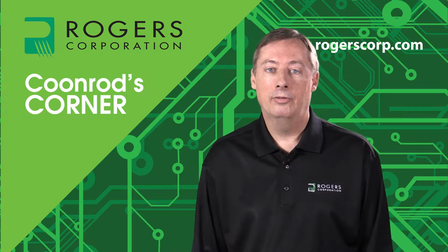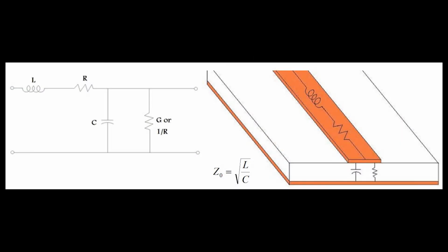So to begin with, let's go through some of the basics of impedance. Shown here is a circuit and also a schematic that is representative of the circuit. The schematic is an RLGC schematic, which means R is resistor, L is inductor, C is capacitance, G is conductance. I have that drawn over a circuit, which is actually a microstrip transmission line circuit. The symbols are drawn there to show you the characteristics of the circuit related to the schematic. This is obviously not a rigorous definition, but it's to give you an impression of how the schematic relates to the circuit itself.